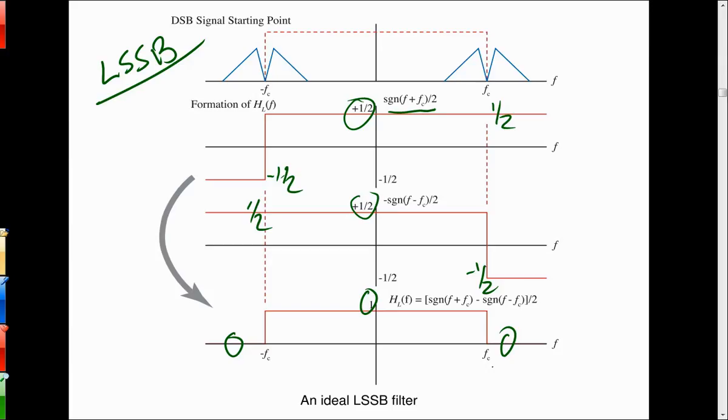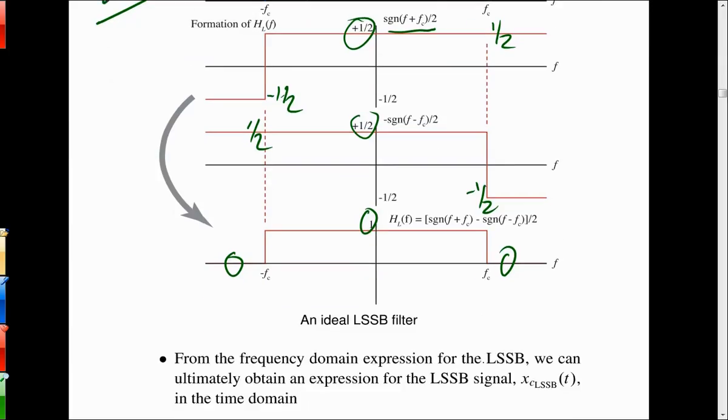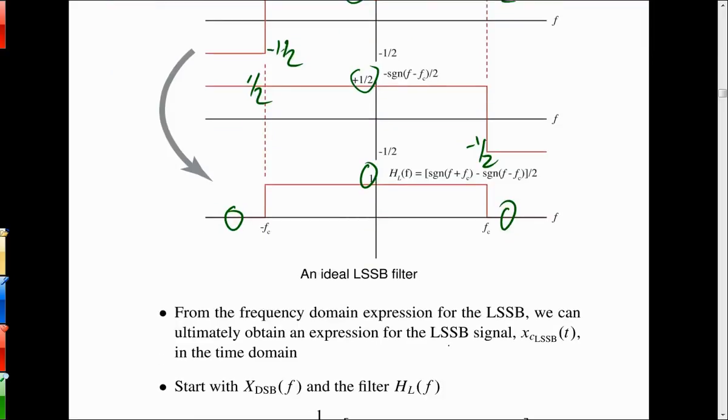Okay, so this is a synthesis, and the long roundabout way was to say we're just synthesizing a theoretical expression that will be ideal if we can implement the Hilbert transforming filter. So now that we have what this filter looks like, this is actually the LSSB filter, the lower single sideband filter.